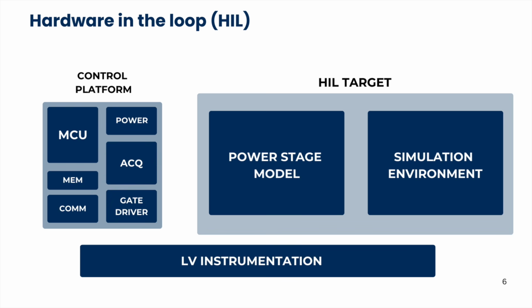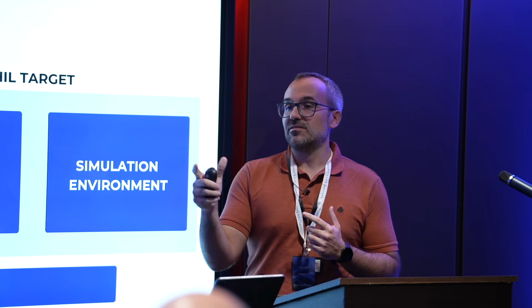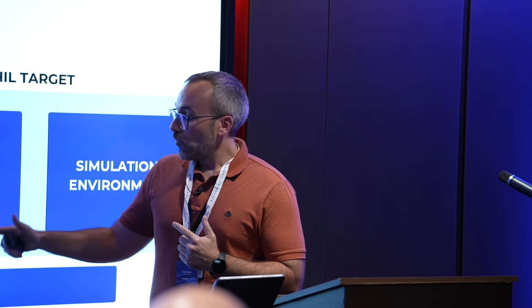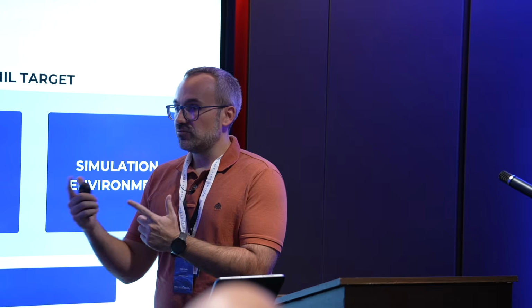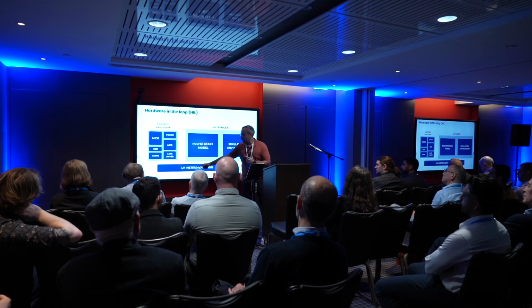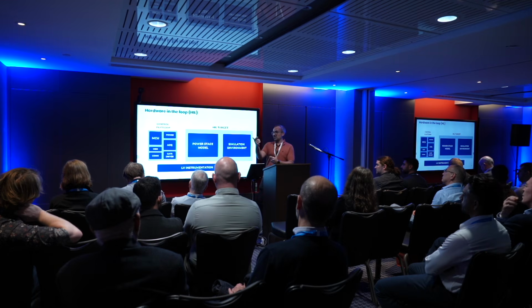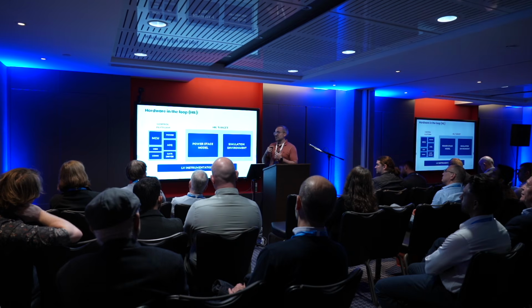In addition, since hardware in the loop targets use low voltage, like 10 volts or 15 volts, we don't need high voltage instrumentation. We're going to be able to take all the measurements just using low voltage instrumentation, like the typical probes we have in our system. But we can go one step forward.